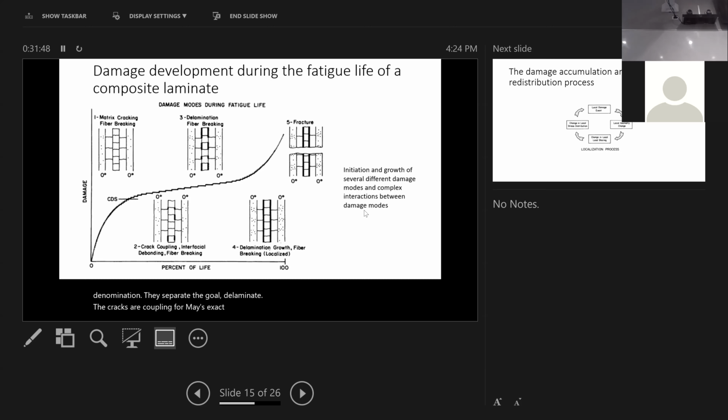These are individual cracks, and they start talking. They now become a delamination. And that process worsens as you go a little bit more, and you have a bigger delamination that makes the two layers separate over a large area. They don't have mutual constraint anymore.